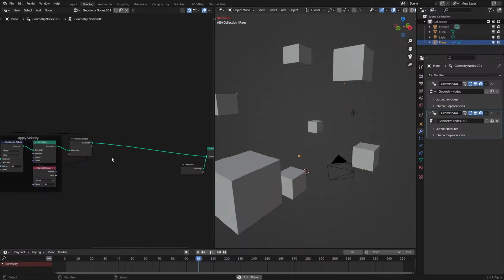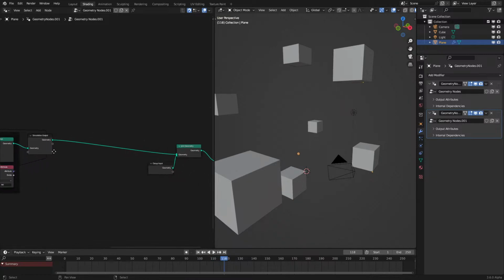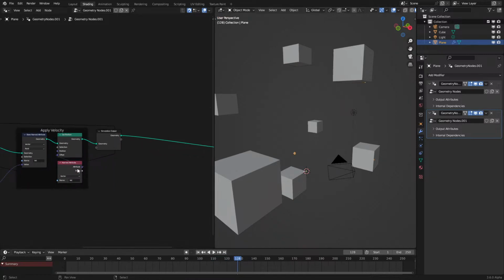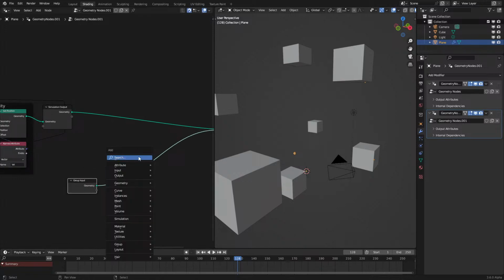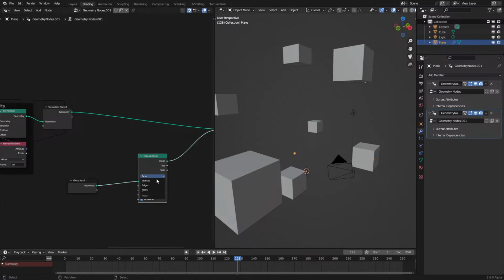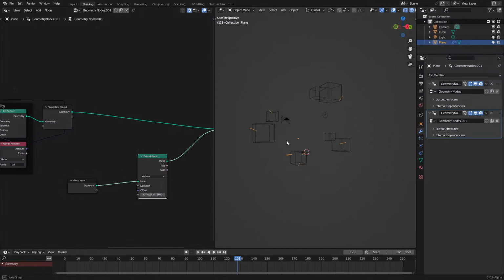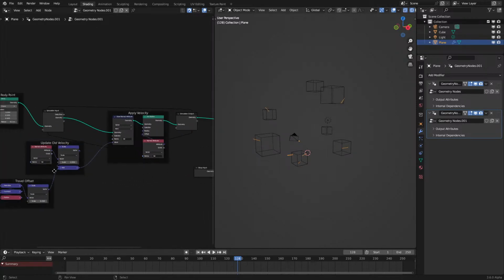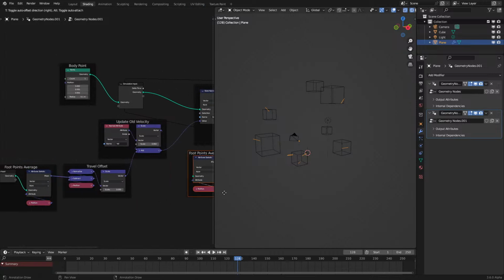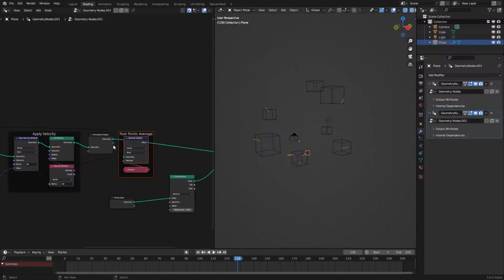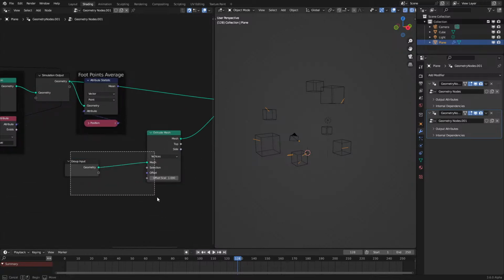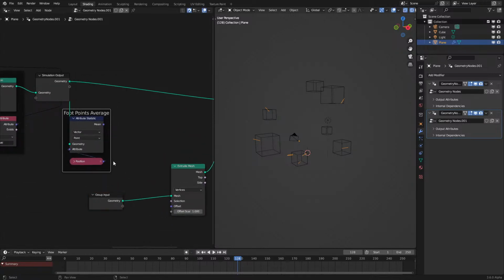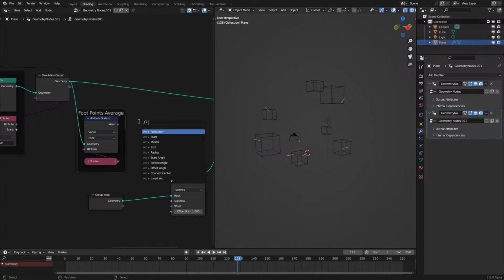We're at 15 minutes, so not bad timing. But now, since we have this average position, we can then go and mesh from the points to there. So that is actually extremely easy. Let me demonstrate. So if we extrude the mesh vertices, we can see that these go in just kind of random locations. But if we use that attribute statistic again, even though there's only one point, this works well either way, we can get the position of the moving point.